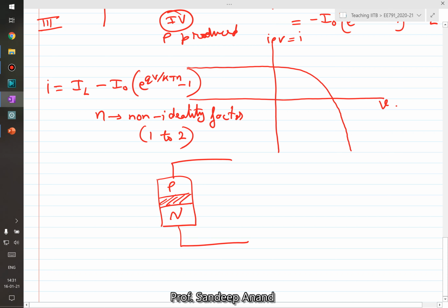You realize now these wires, the one I have shown on the top and the one on the bottom, when they connect with the silicon material, there is a voltage drop in that connection. Plus these wires will also have a resistance drop. Plus when the current flows vertically in this P region or in this N region, still there is a voltage drop. So all of that put together, we can usually represent it as a series resistance.